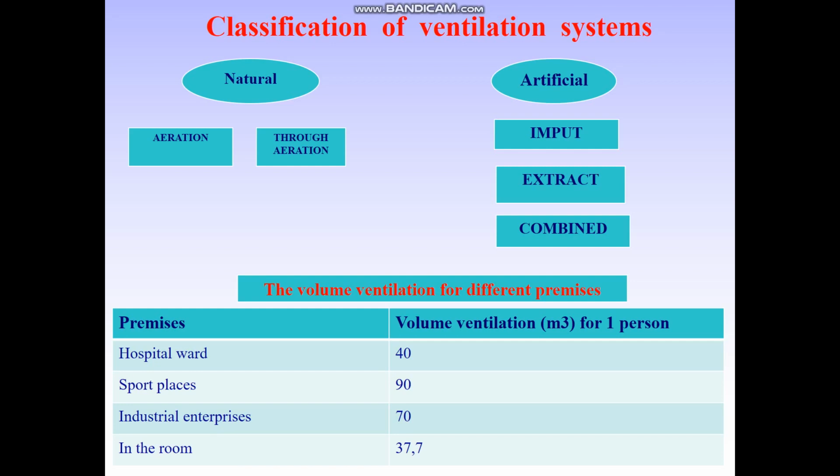The value of required exchange of indoor air with outdoor air depends on the number of people in the room, the character of operations executed by them, and the room cubic capacity. This value can be determined with use of different parameters. One of them, widespread in sanitary practice, is the concentration of carbon dioxide. Ventilation should keep the concentration of carbon dioxide in the air of premises no more than 0.1%. This concentration is adopted as the permissible concentration for usual living rooms, classes, hospital beds.